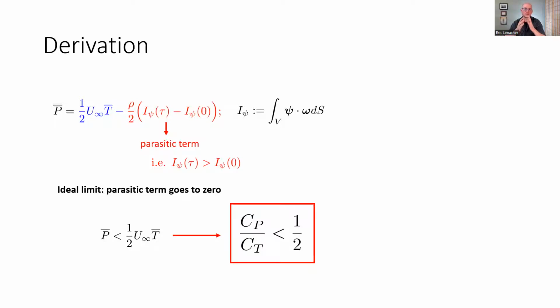Regarding the fact that the wake is growing, the reason that comes into play here and not in traditional analysis is because we haven't defined our control volume such that we have a steady flow inside of it. We've actually just blown that control volume out to infinity, so we don't have any momentum flux at infinity. Rather, we're just relating the thrust to the momentum change inside the domain. I don't know if that answers your specific question or not. Yeah, maybe I have to think about it, but thanks for the answer. Okay.